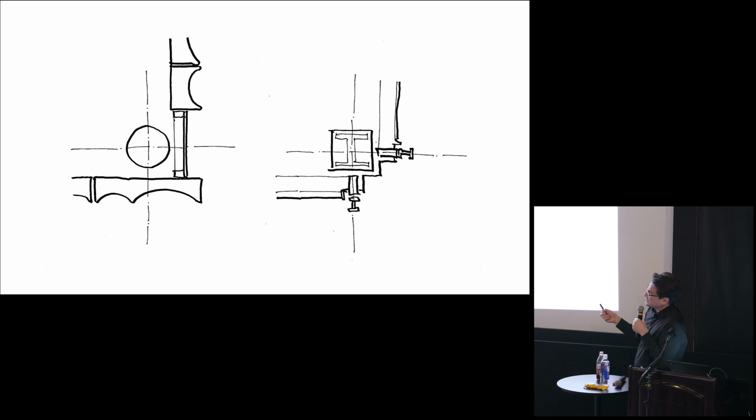And then the spacing of the mullions, it's subdividing that structural bay, right? And if you put the mullion on the column line, then you're always going to have a leftover, right? And what's in that leftover, we don't know. The column size could grow or shrink, but that leftover is what produces the Miesian corner.